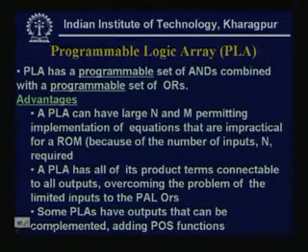Whereas, this PLA can be a very compact thing. Even if n is large, we need only 2n lines, because we need both the literals and their complements.